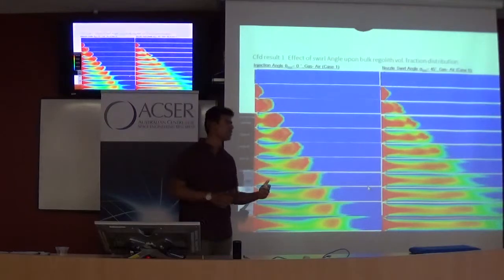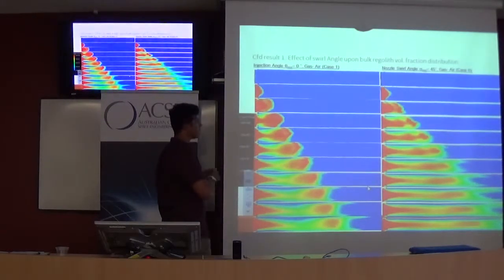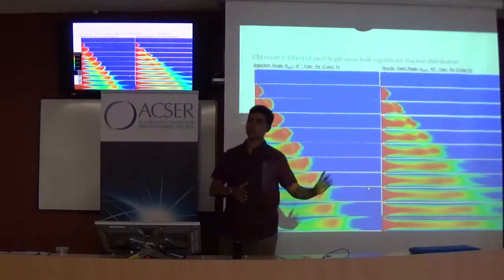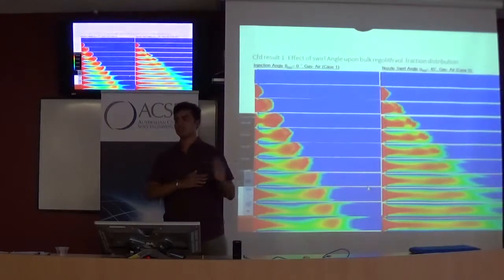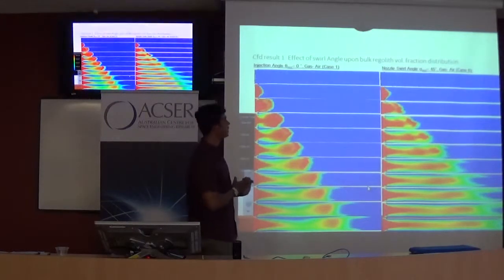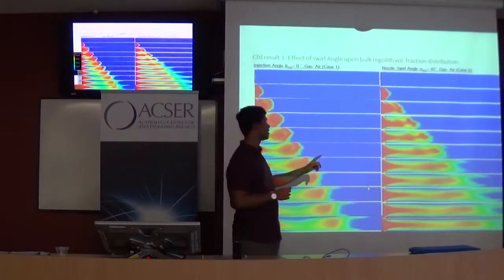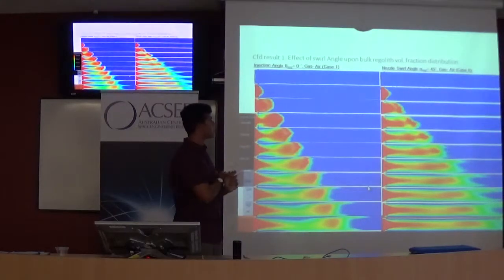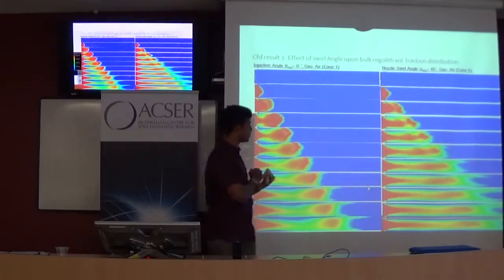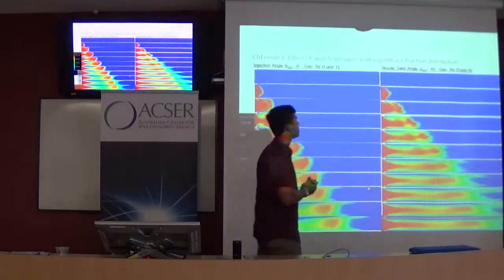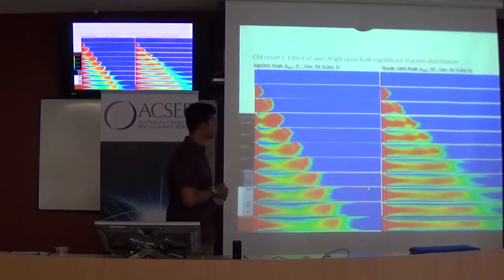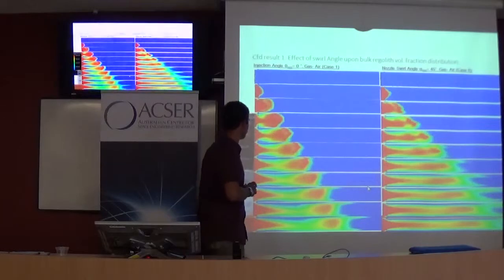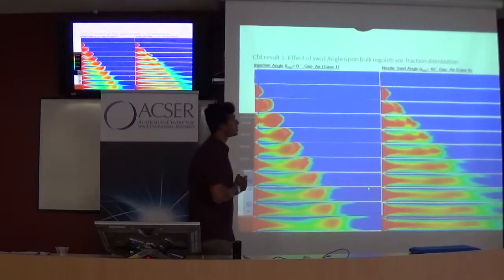for ease of viewing, for you to understand how swirl increases the speed at which the regolith was flowing through and passing between these two tubes. So very quickly you can see the rate at which the regolith was picked up and moved forward. That is the first thing that comes across, that the volume fraction progression is faster when you have a swirl angle. The other thing, which is not so apparent, but you can sort of make out from this time step contour, is the distribution as well.